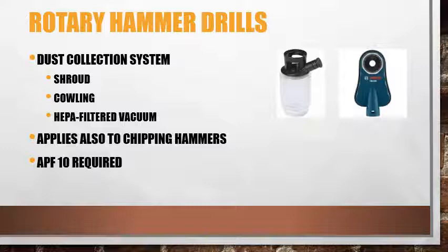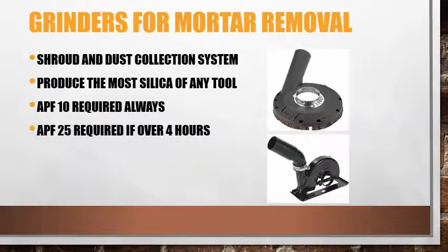If you're using a rotary hammer drill, dust collection systems are necessary. The dust collection systems that are used are either a shroud or a cowling attached to a HEPA filtered vacuum. This also applies to chipping hammers, and an APF10 respirator will be required when using a rotary hammer drill or a chipping hammer.